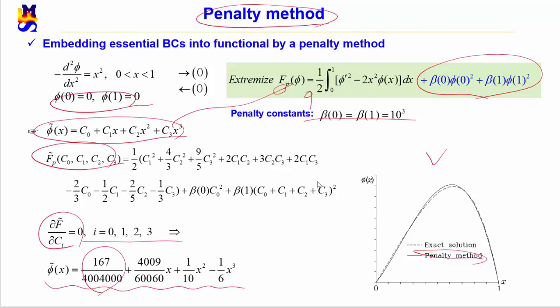Of course, you may think that the penalty function or constant relates some state variables to the physical meaning, as we know that lambda in Lagrange multiplier method has a relationship with slope at the boundaries. Applying first variation to the extended variational principle, you can derive a mathematical relationship between some state variables with physical meaning, which are linked by the penalty functional constant. Please try to obtain the relationship by yourself.